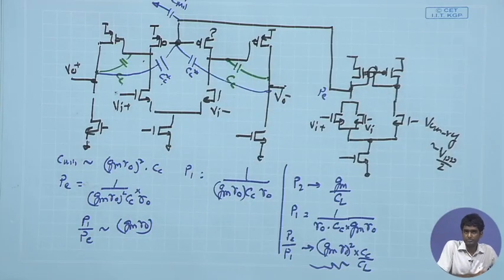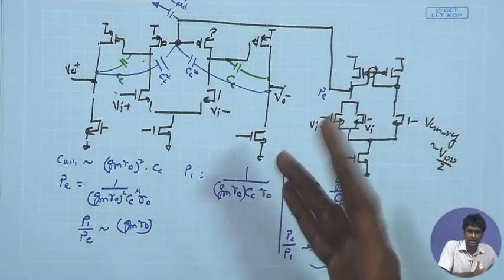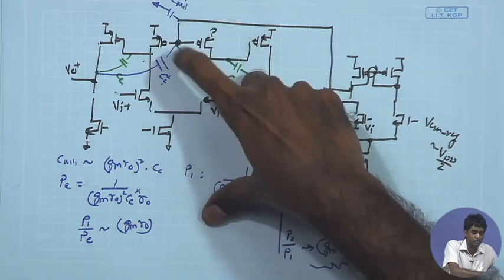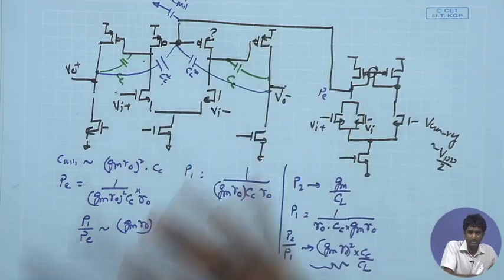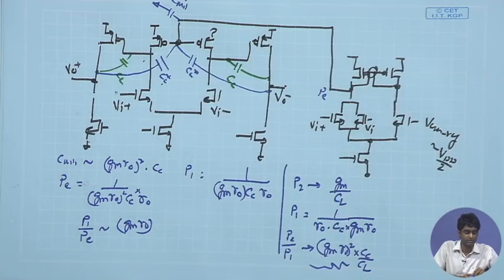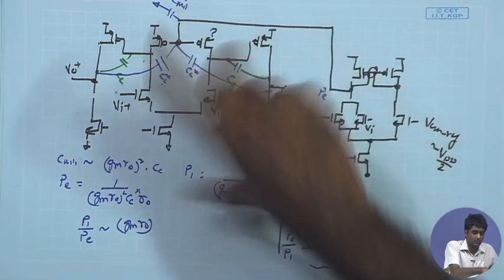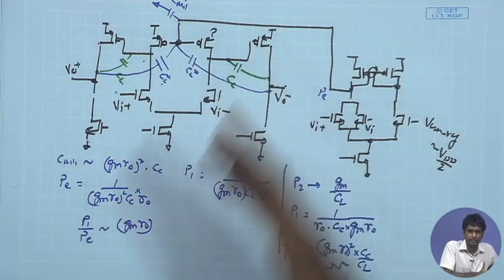So it has, of course, trade-offs with area. So you will have to put a lot of area to obtain an overall 45-degree phase margin for this scheme. Advantage will be that yes, you can compensate the two loops in a very different fashion. You can have the common mode loop with much lower bandwidth as compared to the differential loop.